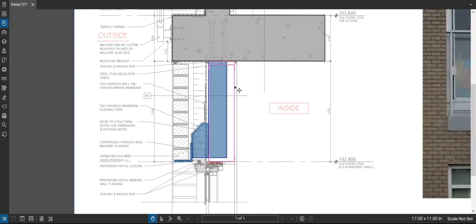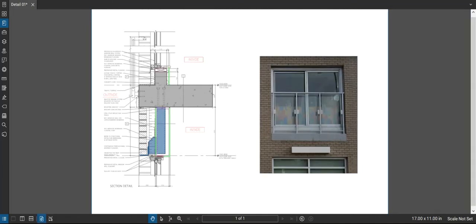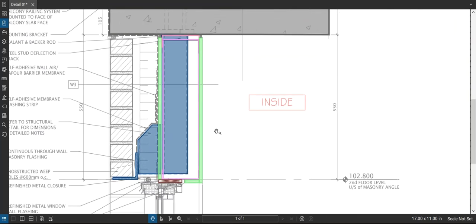Okay, next here we'll take a look at the sheathing that's been put on the studs and the gypsum board on the inside. Okay, so I've highlighted the sheathing and gypsum boards in green here. So there's a glass mat sheathing. This would be a non-combustible building, so it wouldn't be plywood, or it wouldn't be OSB board. It would be a glass mat sheathing, which I'll show a picture of in a minute. And then on the inside here, they've got gypsum board.